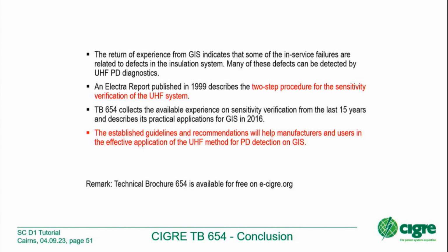No, from my point of view, and I'm now a third-party university guy, I can say that the GIS manufacturers are responsible, from my point of view, to ensure a lifetime of 50 years plus. And so the manufacturers should have an own interest in a high quality of the product, not only for the beginning, 1 to 2 years, also for the long lifetime. And that's my personal viewpoint. You have to look for highest sensitivity to detect all possible defects. And nowadays, that means you have to go for detection of protrusions. I'm pretty sure you have a different opinion. Yeah? So the end of the story is that the customer, the utility should specify what they really want to have. Then it's clear.